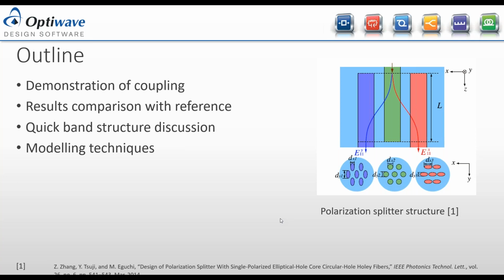Just like a single mode fiber, it's called single mode, but it actually supports 2 different modes. One could be an x-polarized mode, and one could be a y-polarized mode, right? There are 2 independent ones. And of course, any combination, you could have a 45-degree polarized mode that would be made up of the two X and Y polarized modes.